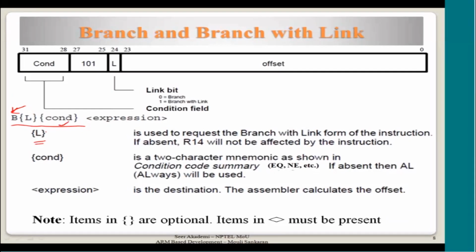If this condition is true, the branch is taken. You can add the condition inside, and then what will be here? It will be a label. A label means an assembly label. In the assembly, a particular instruction will be associated with some label, and that address will be computed based on this instruction. Now, how does this particular instruction help in computing it?